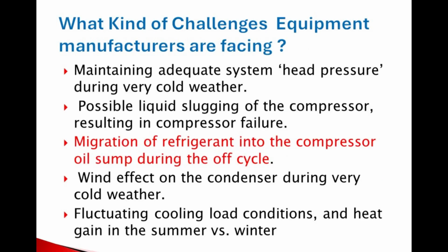3. Avoiding refrigerant migration. A factory-installed crankcase heater circuit is energized during the compressor's off-cycle to prevent liquid refrigerant from migrating and condensing in the compressor oil sump, thus preserving compressor bearing lubrication and preventing premature failure.